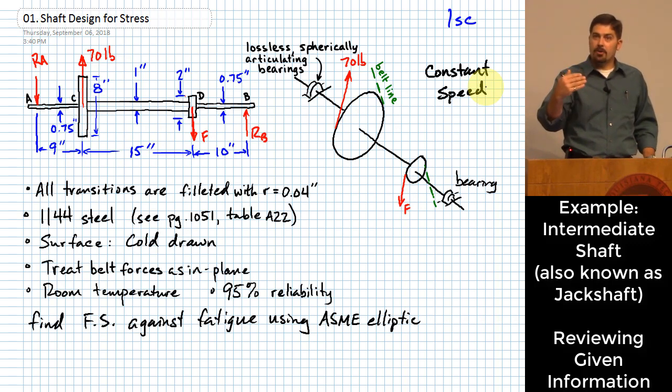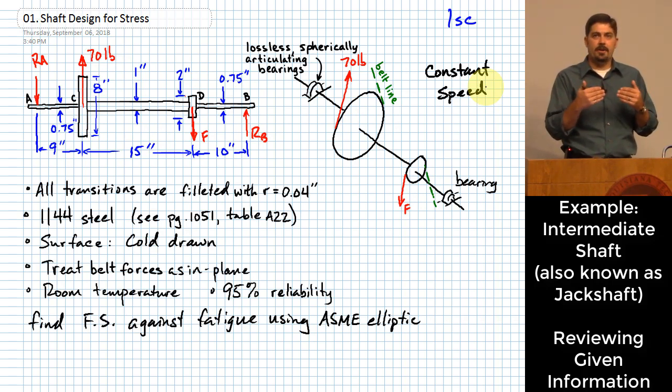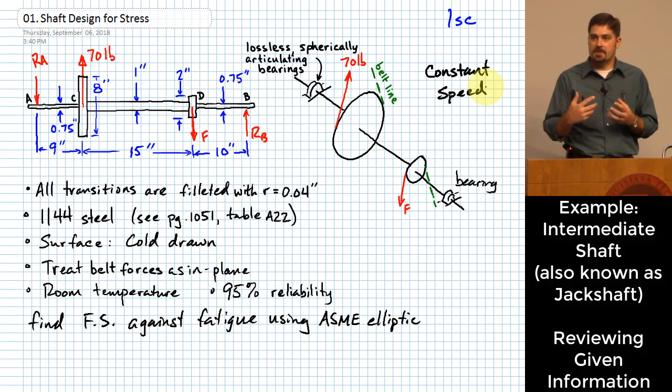And the more micro cracks and the more severe that they are, that gives us a larger number of sites where fatigue processes might initiate, right? And so that will increase a body's susceptibility to failing in fatigue. If it's got a rough surface, typically it is more susceptible to failing in fatigue.